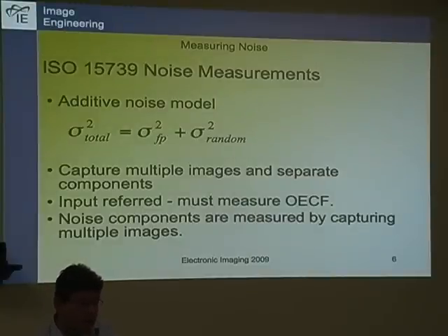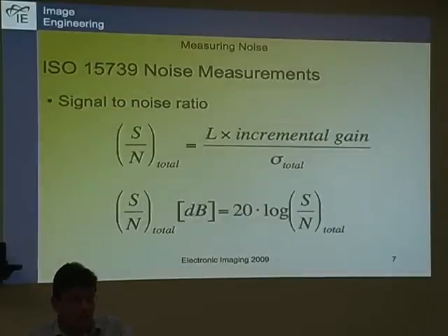And typically from this you compute the signal to noise ratio, and since you can apply tonal correction like gamma curves or similar things to an image, this signal to noise ratio, which would be completely linear for a system that has no image processing, is corrected with the incremental gain at the certain position.